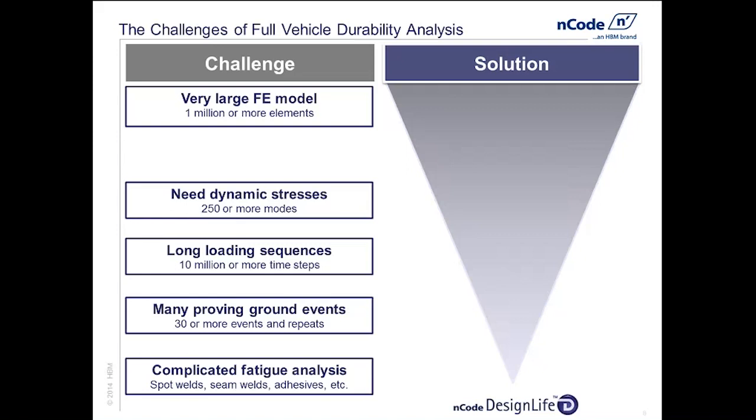Third one down, long loading sequences. What I mean by that is the time series data that describes how our part is actually used, the wave loading on an oil structure or the road loading into a vehicle frame. That can be many, many millions of time steps to really fully capture the variability of different drivers, different users, different weather conditions, and so on. So if we're not careful, we can end up with a lot of time steps that we need to solve for stress. So we need a better way of dealing with long time series.